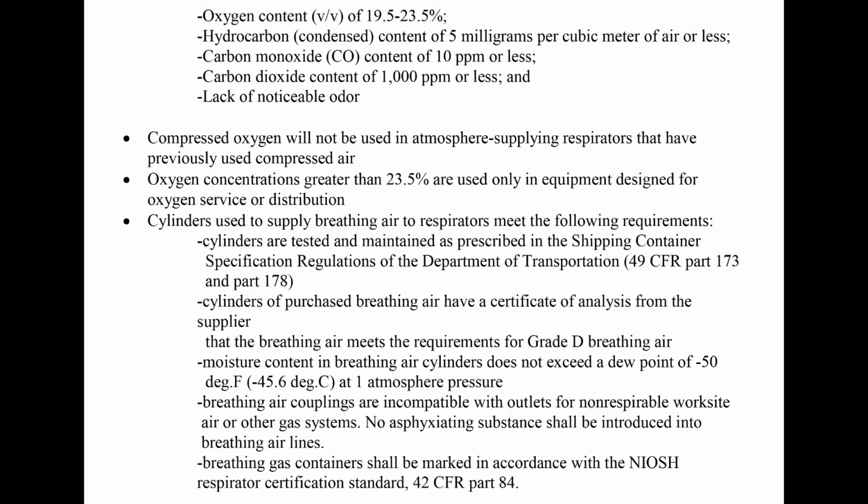Cylinders used to supply breathing air to respirators meet the following requirements. Cylinders are tested and maintained as prescribed in the shipping container specification regulations of the Department of Transportation, 49 CFR Part 173 and Part 178. Cylinders of purchased breathing air have a certificate of analysis from the supplier that the breathing air meets the requirements for grade D breathing air. Moisture content in breathing air cylinders does not exceed a dew point of minus 50 degrees F, minus 45.6 degrees Celsius, at 1 atmosphere pressure.